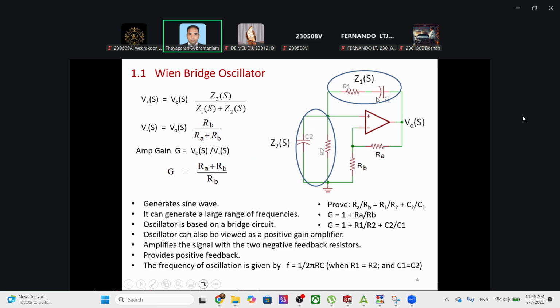By changing the capacitance values, we see what frequency we have. You have plots. Then you can bring your own unknown capacitance, place it here, get the output frequency and project it, and you will get the capacitance value. That means we do a backward calculation. We know omega, therefore what would be the C1?